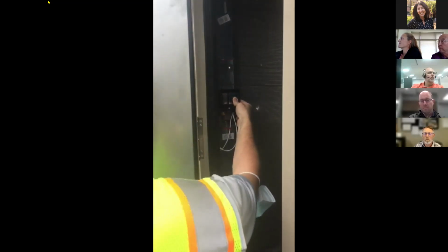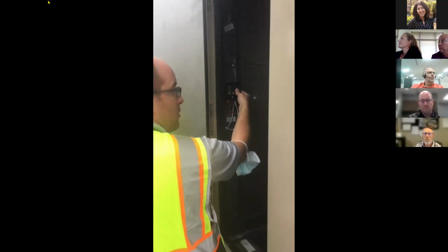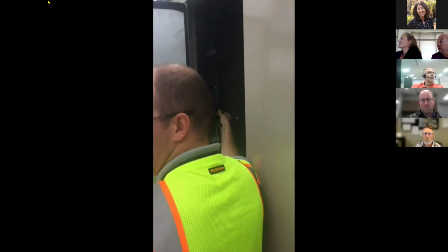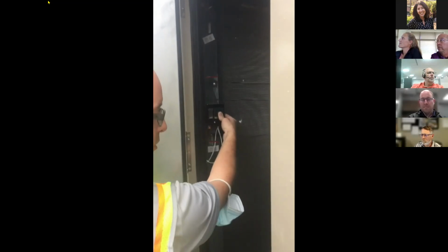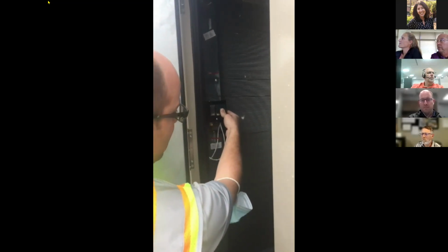You've got to hold it in, but you should be able to hear valves close. And if you have a helpful hand, you can also check the dampers are shutting. Outdoor damper shut, return dampers open, whatever your sequence of operations calls for. And then when you're done, you've heard everything you need, seen what you need, just release it, and the unit goes back into auto, just as we expected.